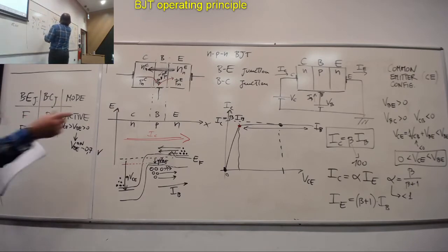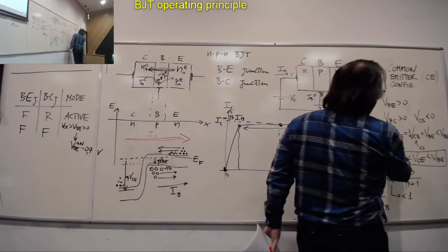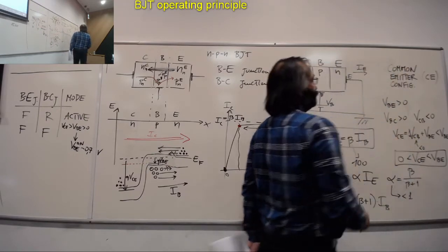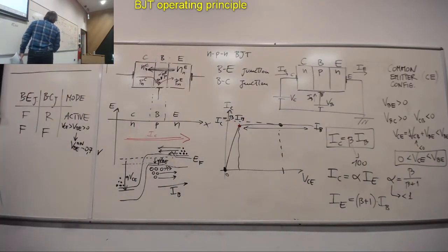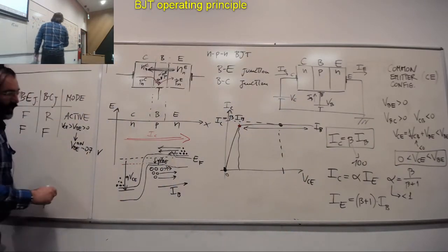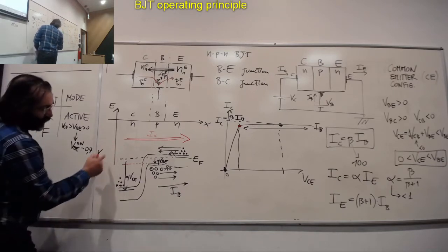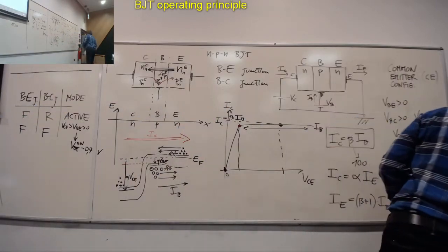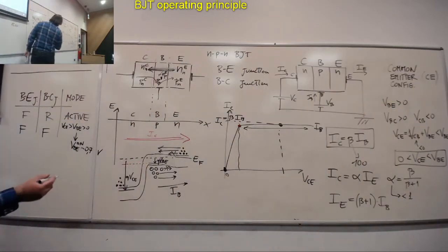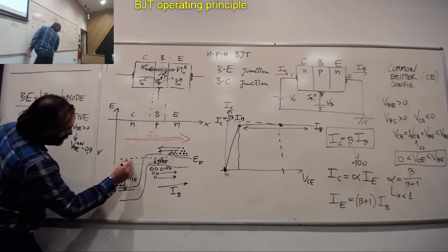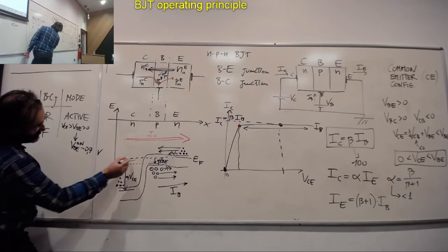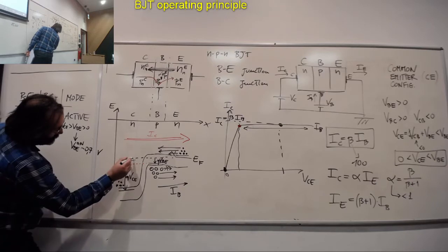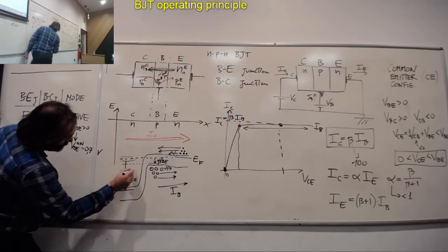That is VBC effectively 0. You see, when VCE is equal to VB it means VCB or VBC is 0. So from that point on, if I was to draw, I don't want to make a mess of the diagram, I will do it in blue. So let me draw a situation where the Fermi level is slightly below, in between the black and the red. And so this is an N-type, so I should draw it like that, something like that.